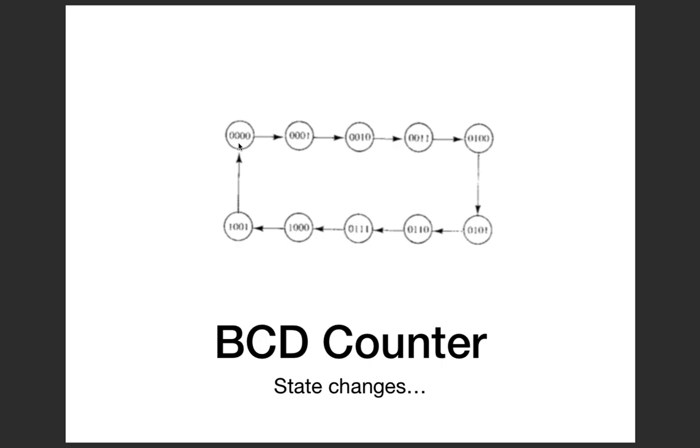So what's the difference now? Earlier, naturally the count became 0 after it reached 1 1 1 1. But now 1001 will not naturally cycle to 0000, because the counter will give a value of 1010 next. So it's not a naturally designed counter like what we have done till now. How can we do that? If you look at this, there is one situation where we have to manually reset the count back to 0. And which is the situation?